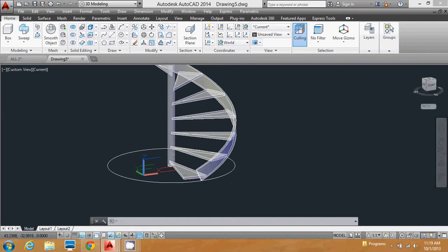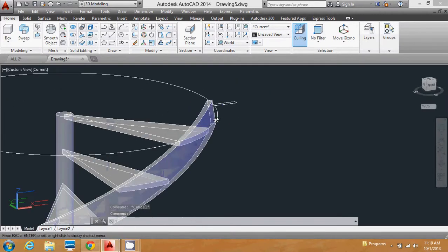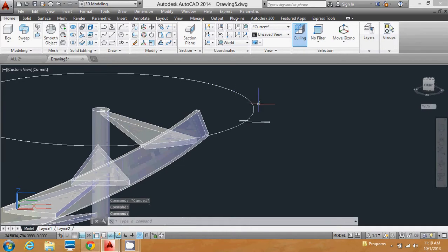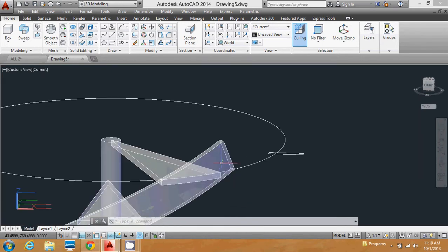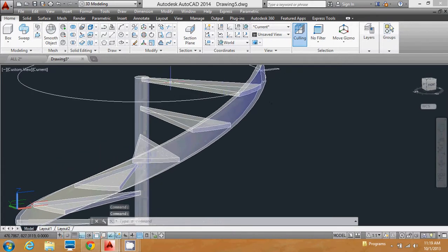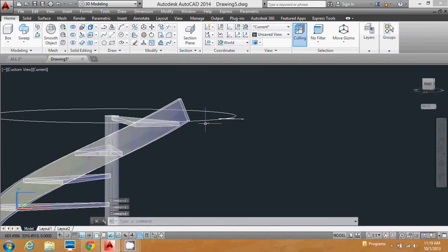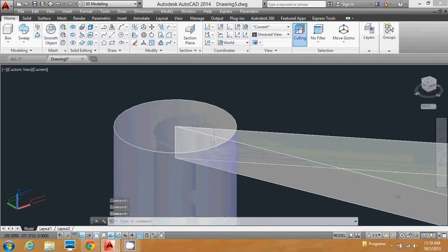So the next step will be to close it out at the bottom. And, well, depending on how the floor is set out, you may want to extend it or not. Now there's a few different ways you can do that. You can draw in the helix and go up and then add some more material. Or if you believe that this floor is actually perfect, and the floor of the cylinder is the correct size, I'll show you an example of what I mean.